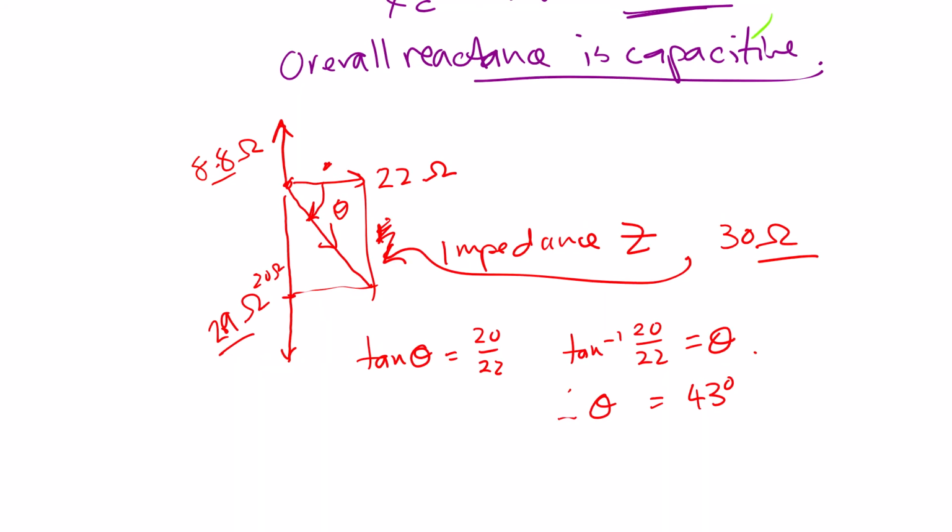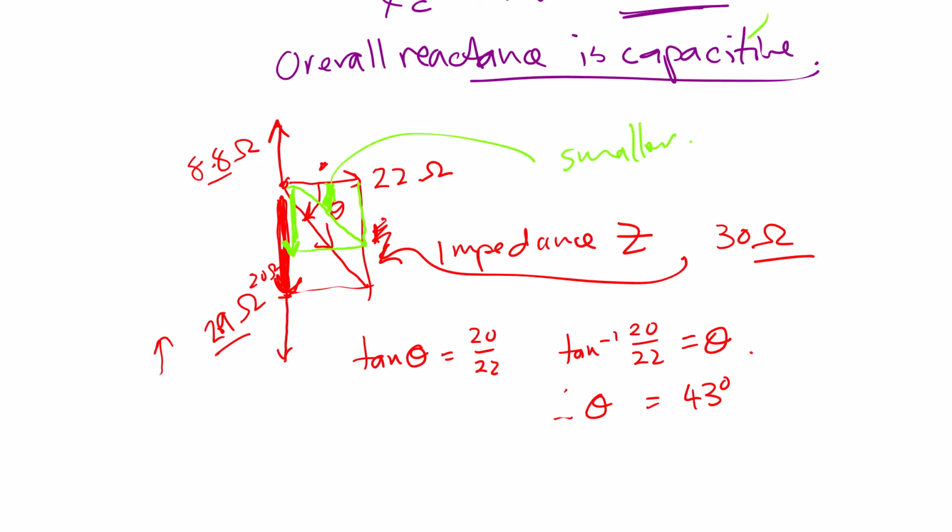So let's have a look at our graph, I mean phasor diagram. Let's have a look at this. As the capacitance increases, our reactance decreases. So we started out with this reactance, and this reactance will get smaller, maybe coming down to here. So what then of our overall impedance? It is this, and we can see this angle is a smaller angle. So that increased capacitance decreases the capacitive reactance, and that decreases the phase angle. The phase angle there.